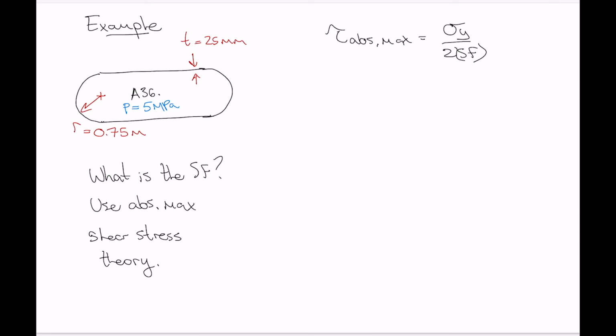Okay, in the tank wall, all points are under the same stress, so this is the nice thing about pressure vessels, they're dead simple. So we'll take this point as an example, and we know that we've got stresses sigma H and sigma L, like that. Now, that is only true if the pressure vessel meets the thin wall assumption, where radial stress is 0. So let's check the thin wall assumption before we calculate those two stresses.